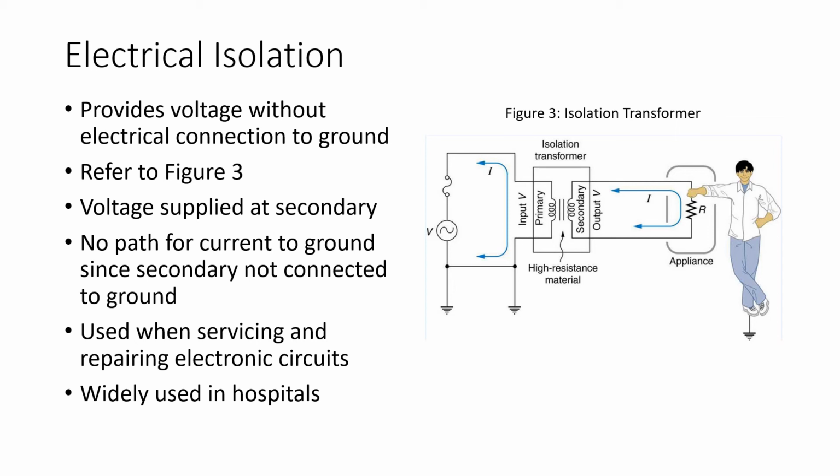So in hospital rooms, they will always provide isolated receptacles, again, that are obtaining their voltage through an isolation transformer.